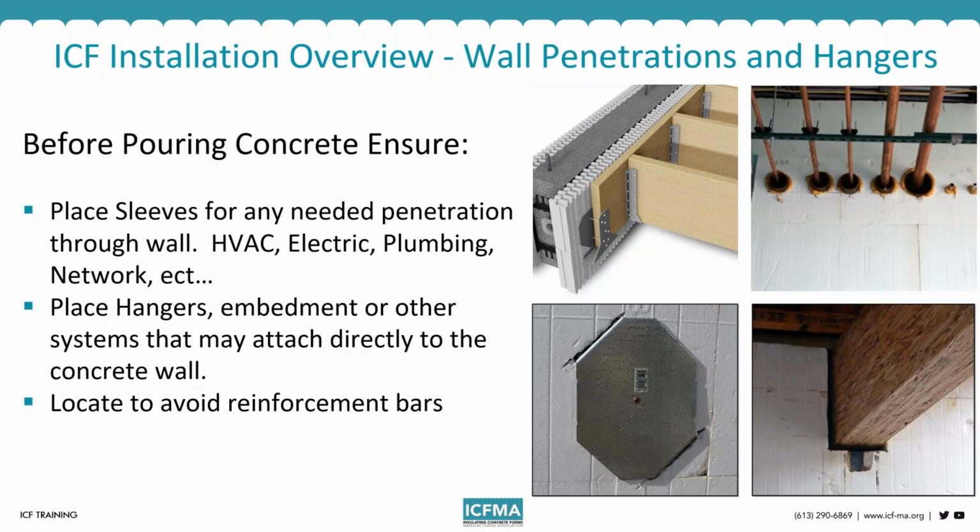There's also many other ways to attach to the block. So depending on your specific needs, there's going to be different penetrations or different systems that allow you to create embedments. So depending on what you're trying to attach to the wall, how you're doing your floor systems, or how you're doing your other mechanical systems, it's best to do a little bit of pre-planning before you get to the concrete phase, so that you ensure that you've made all the penetrations and things necessary to get through that wall. It's no fun to have to go back and core that wall to make penetrations for anything mechanical or to do other types of things.